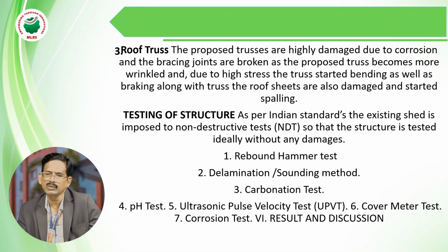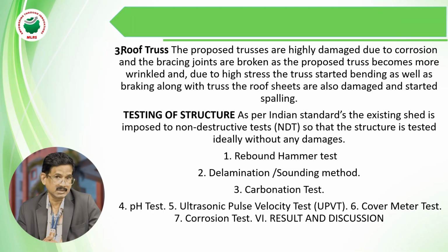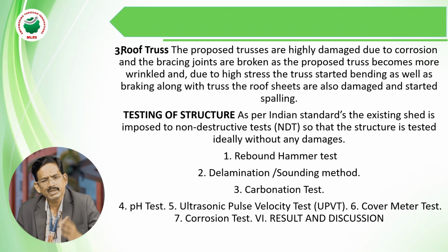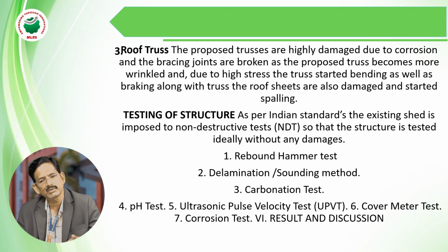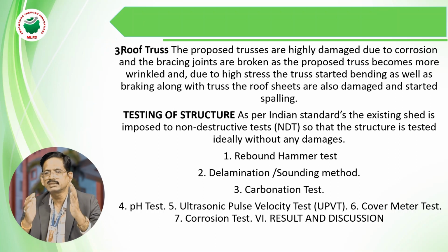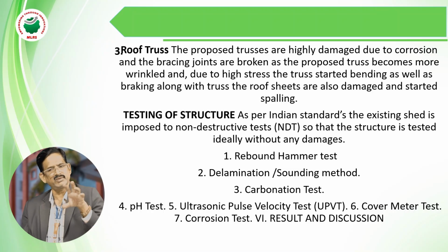So we have to follow the proper design mix, whether you have to go for quality of the material, quality of the labor, quality of the inspection, and quality of the scaffolding. Whether the scaffolding is to be removed as per the standards or not. For columns, as per the code book IS 456, it is 24 to 48 hours. So instead of a minimum of 24 to a maximum of 48 hours, if you remove the scaffolding in 10 or 12 hours, you don't get the original strength. So that's why the deviations.